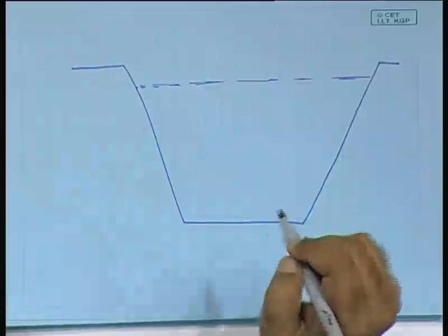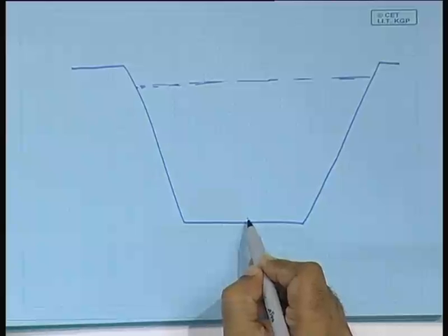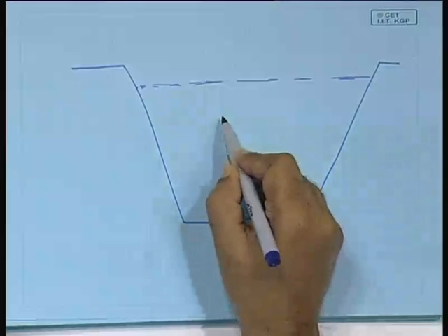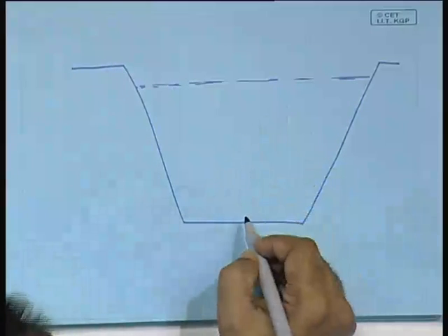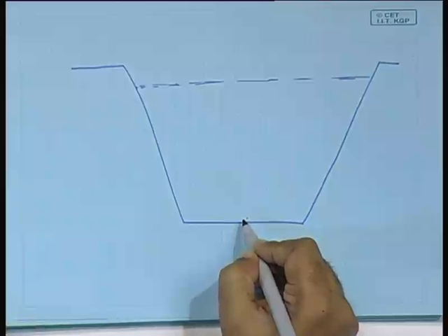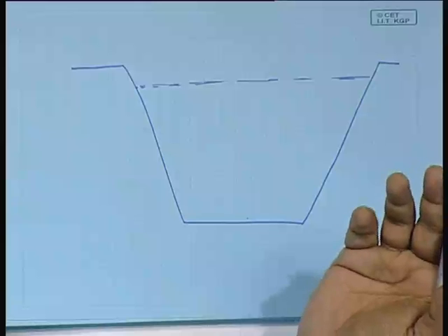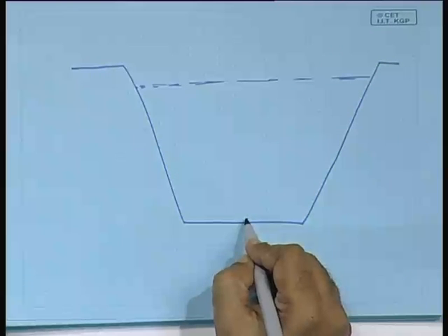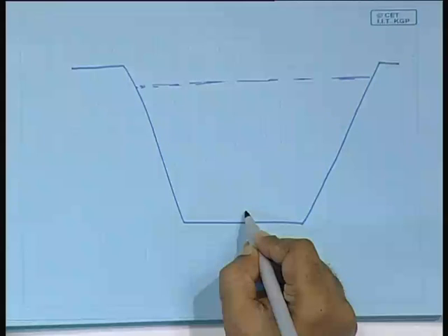Because here, if the water is heated up, its density relatively at least becomes lower than the density here, so it rises. So, if somehow you can increase the density here by some other means, so that the density cannot go below the density at the relatively upper level, then obviously it gets trapped.